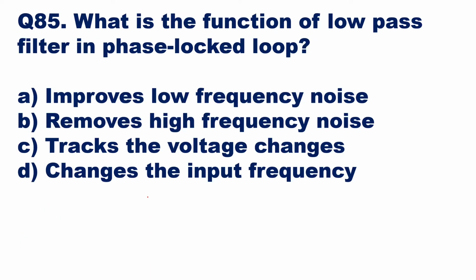Then we'll go to the next question, question number 85. What is the function of low pass filter in phase lock loop? Okay, so if you remember the block diagram of phase lock loop, there is a low pass filter used in a PLL block diagram. Now for what it is used? Here options given are it improves low frequency noise, it removes high frequency noise, it tracks the voltage changes, it changes the input frequency. So low pass filter is one which will remove high frequencies. It will not allow high frequencies to pass. That means option B is the right answer. It removes high frequency noise.